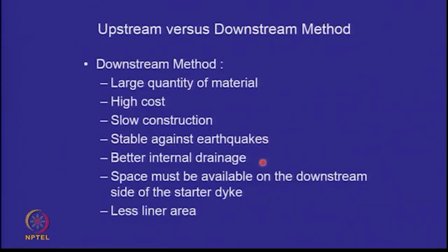It's stable against earthquakes. Nothing is resting on loose deposit. It has better internal drainage. We'll see this at a later stage. However, space must be available on the downstream side of the starter dike. If you don't have the space, you can't expand on the downstream side.